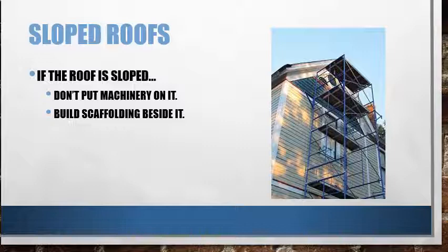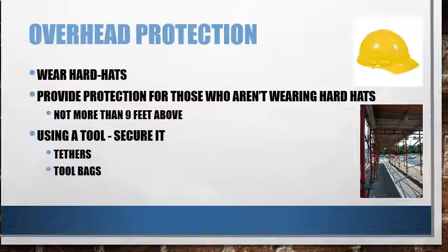OSHA also requires us to discuss sloped roofs. We don't work on roofs that are sloped very often, but if the roof is sloped, don't put machinery on it, and build scaffolding beside it so you can access the roof safely.